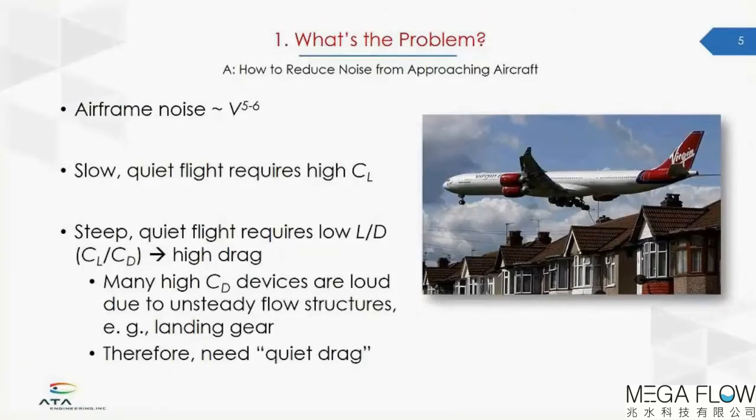It turns out for a turbofan-powered aircraft, scaling from small business jets out to large commercial aircraft, if you want to go about a degree steeper, you need about the same drag as a bluff body with the area cross-section of your propulsion system, or about a little bit less than 2% of your landing weight. If you want to go 3 degrees steeper, you need 3 times that drag. And it's also worth noting that if we are looking for drag, then any residual thrust that our engines are producing are kind of opposing our objectives.